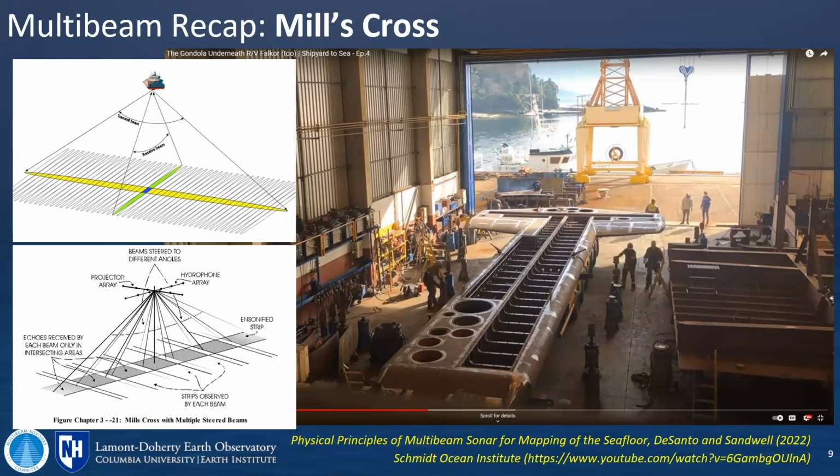Each of those systems is achieving a certain beam pattern, one in transmit, one in receive. You cross those and you get a single narrow beam. And every single bit of beam forming, of beam steering, is happening for each of those beams. In some cases with the new EM systems, you have over 1,000 of these beam products in each slot. And then sometimes you have a dual slot system. So this is happening 2,000 times per beam cycle.